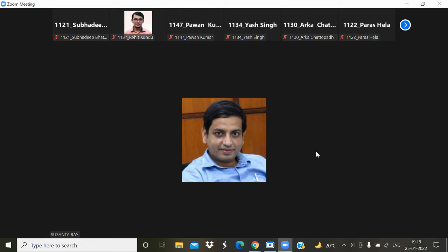So we should assume 3 constants here. That is the designer's choice. What are the 3 constants? Winding factor Kw, specific magnetic loading or average flux density B average, and specific electric loading, ampere conductor AC. These are the 3 things you have to assume as a designer, and you have to put these values in the expression of C0 to find out the C0 value.